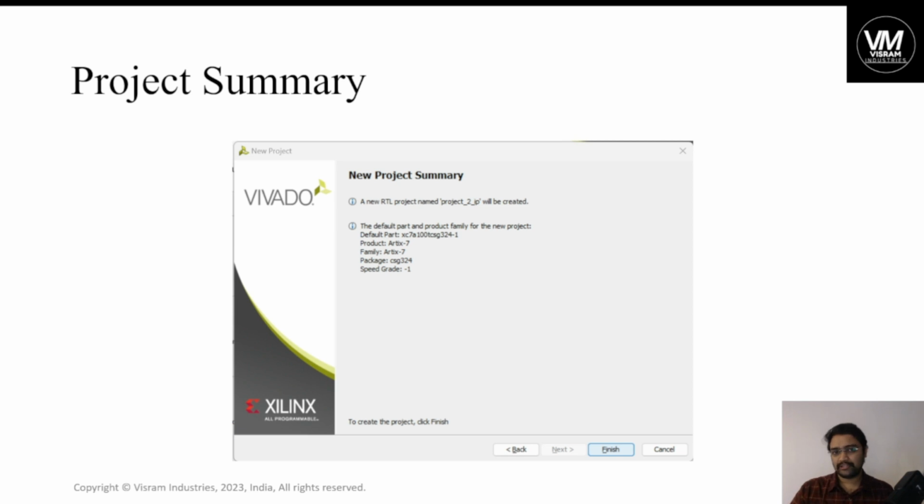I will show you a little bit, and I won't be writing any VHDL or any other thing. The tool will be giving me VHDL after designing the block. So yeah, this is the summary, guys. You can see it has already taken the Artix-7 family because we have mentioned CSG324. That's a package name. We go through the series, and the default part is XC7A100TCSG324-1.